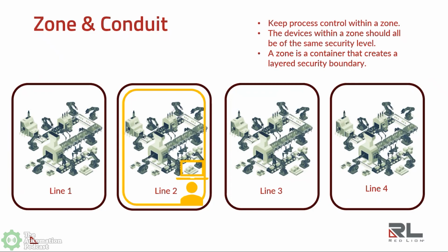And so you're going to do a security assessment before you start something like this. A security assessment is going to determine what security level is required for all of the different devices that you want to secure, and all the devices within one zone should be of the same security level. That creates these boundaries around your application, or portions of your application, that are protected.